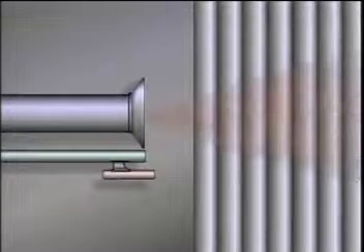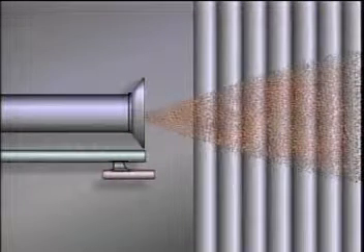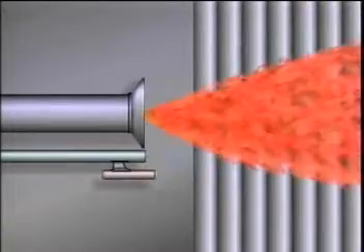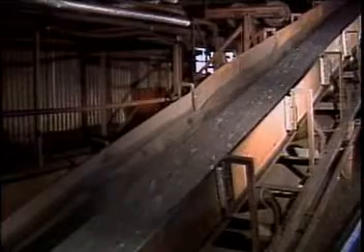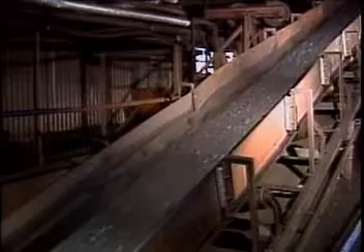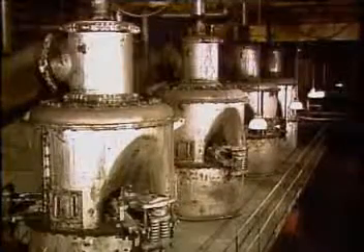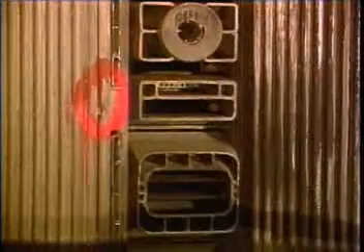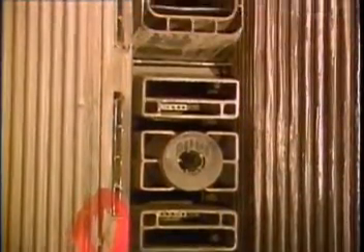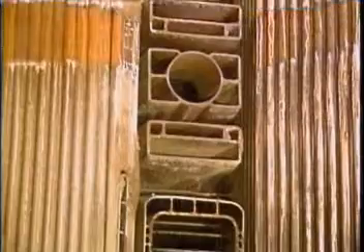Oil must first be atomized, that is, broken into small droplets before it can mix with air. Coal often requires even more preparation. In most cases, coal must be pulverized into powder-like granules before it will readily mix with air. Regardless of the fuel used, a boiler's burners are designed to optimize the elements of combustion so that it will be as complete and efficient as possible.